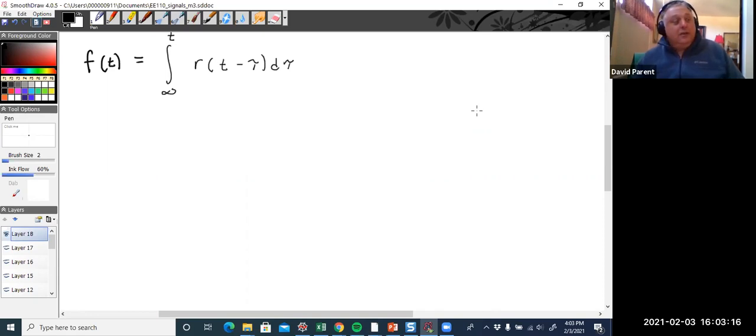And so what will happen is if I put a delta function into a system and measure it, I can find the step and the ramp response by manipulating the output. I don't have to send in a step function to find the step function and a ramp to find the ramp. All I need is one, and then I can mathematically determine everything else. All right.